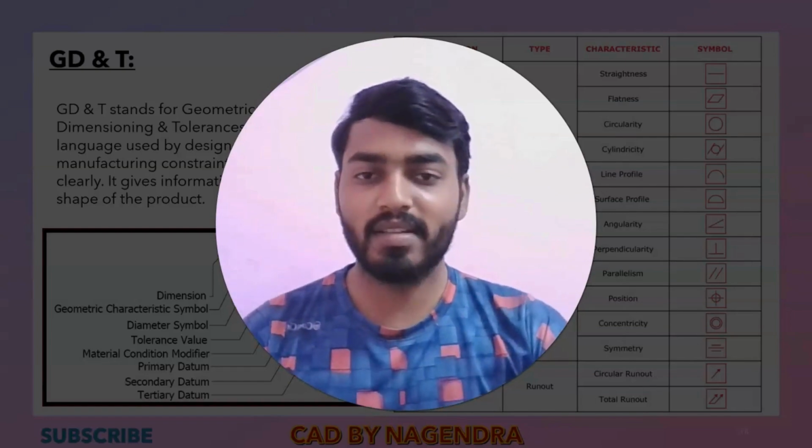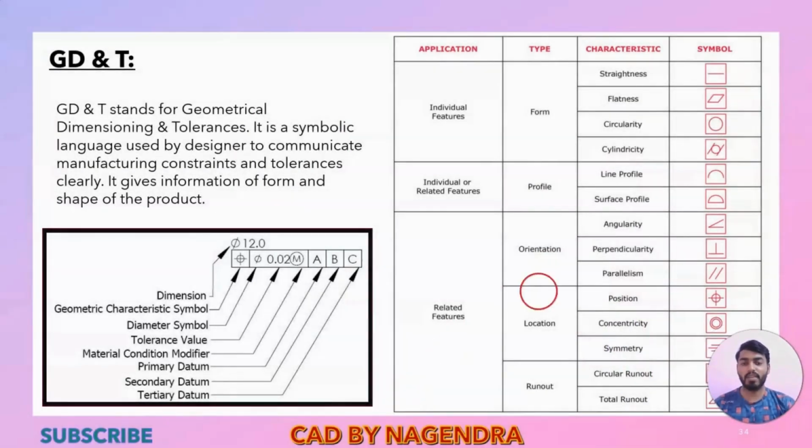So in such conditions, just by using dimensions, you can't define which shape we want. So here we will use these GD&T symbols. In GD&T we have a total of 14 symbols in 5 categories. First the form category: under that we have straightness, flatness, circularity, cylindricity.